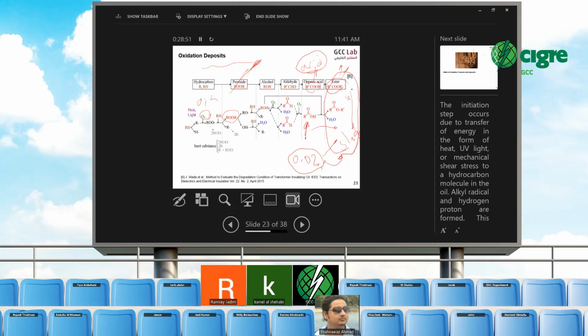It should be this ester. It should be a new thing to be used in the evaluation of oxidation. But that doesn't mean it's the main one. The main one is the acid here. But this one gives me more information, but the main one for you is the acid. The more the acid, we tell you to do direct oil regeneration in the next maintenance plan.